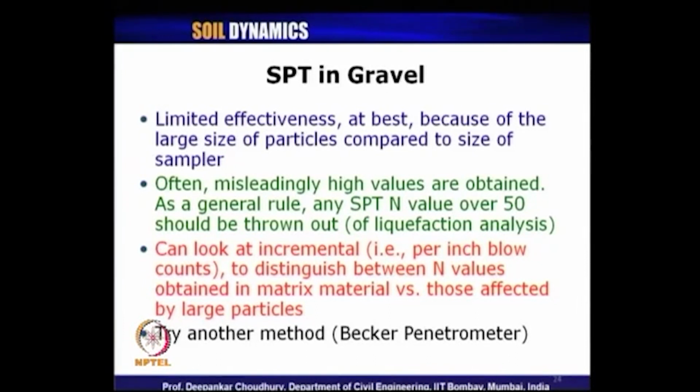Now, sometimes the standard penetration test is also used for gravels, though it is very good for sandy type of soil mostly. In gravels SPT has limited effectiveness at best because of the larger size of the particles compared to the size of the sampler. So, many times whatever SPT N value you get may be misleading, because whatever size of sampler tube you are using, the gravel size can be bigger than that. So, it will not give you the proper SPT N value.